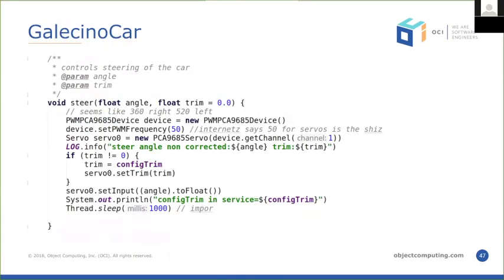Here's how we steer using that Robo4J library. So they were nice enough to build pre-compiled, JNI-based things. One is you can access the device directly. They also have a higher level API here. So if you're using their framework in its entirety, you can do that. But we're just using one of their classes they're using internally called this PCA 9685 device, which gives you a nice thing. When you initialize it, 50 hertz is the correct value for steering. 20 seems to work very squirrely, so I don't recommend that.